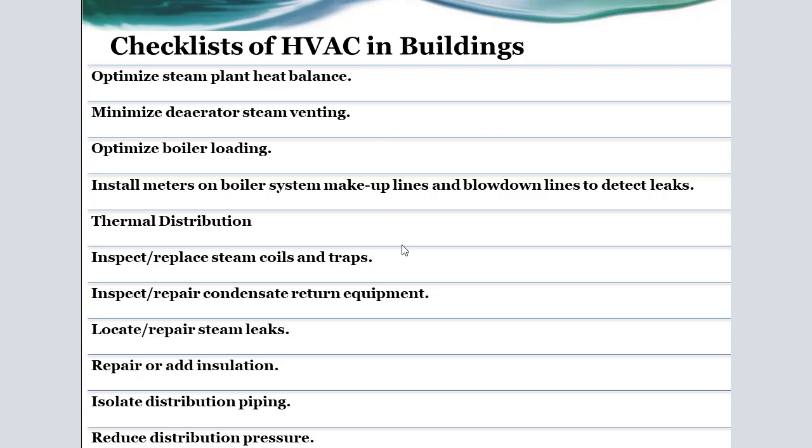This may also include inspection or repair of condensate return equipment of the boiler systems, and finding and repairing steam leakage, and repairing or adding insulation.